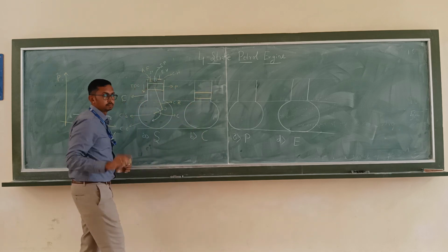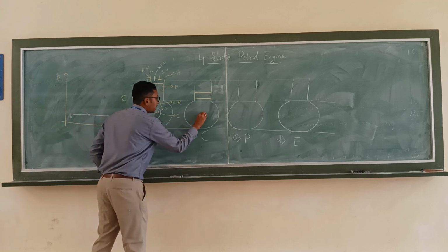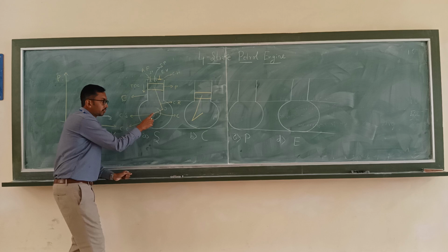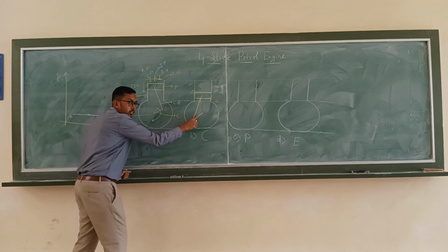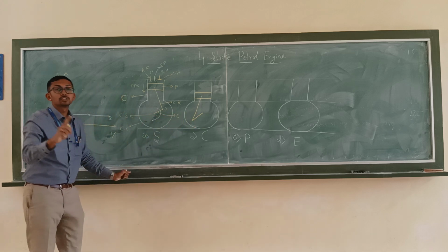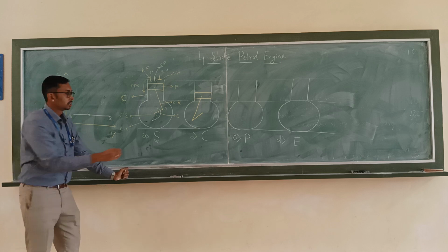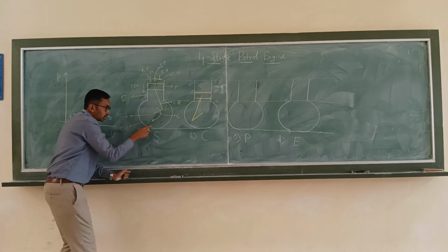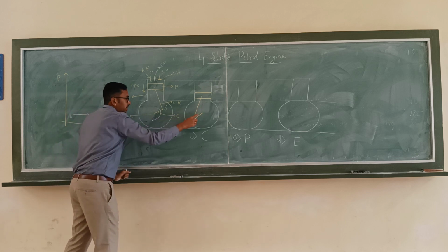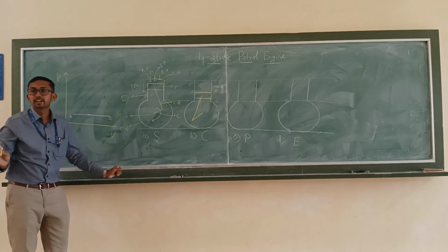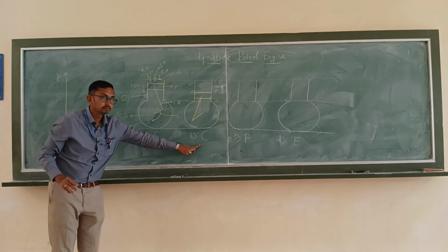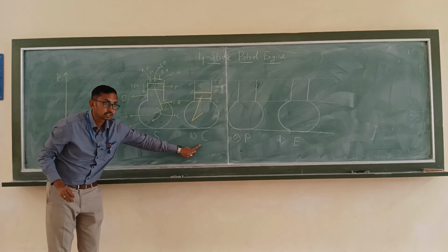Bottom dead center, right? So the crank has to be rotated by how many degrees? See the difference from this to this. There must be a difference of 180 degrees. Suppose this is 0 degrees, and we have given a rotation like this. So this is a distance of how much? Approximately 180 degrees. Now which stroke are we in? We are in the compression stroke.